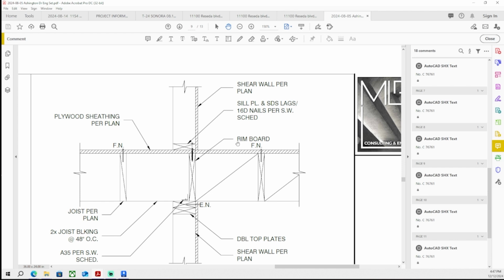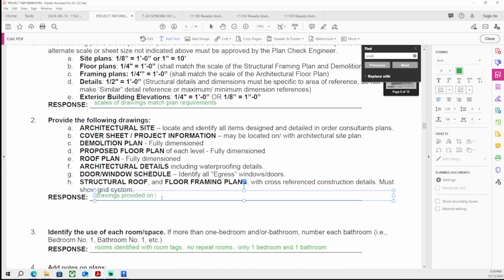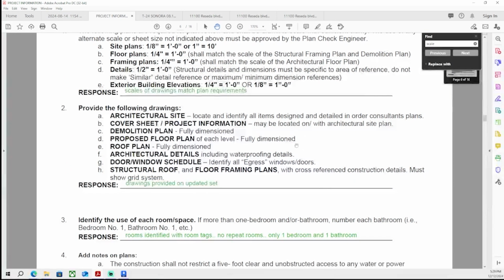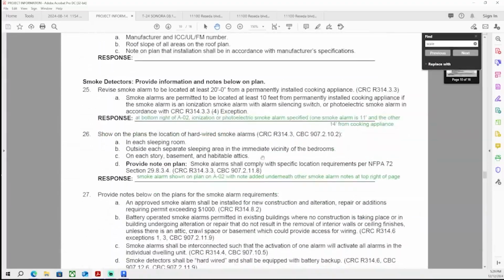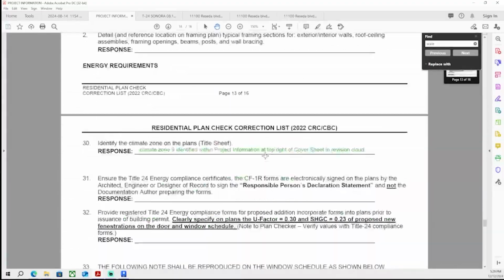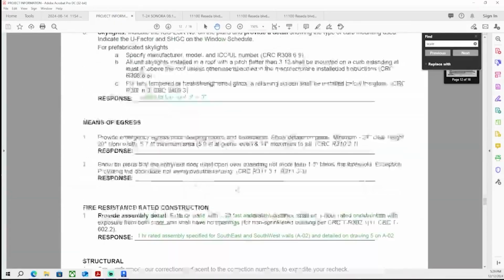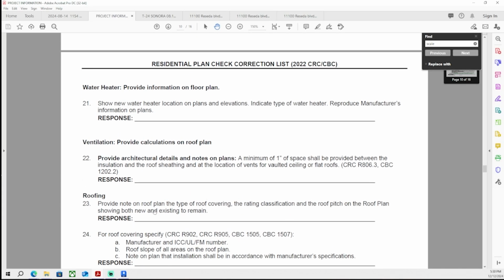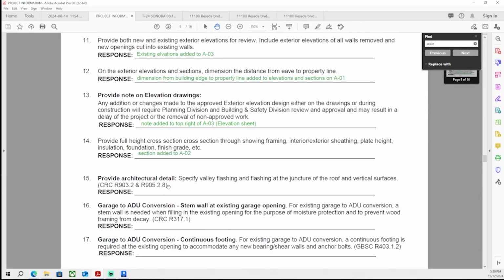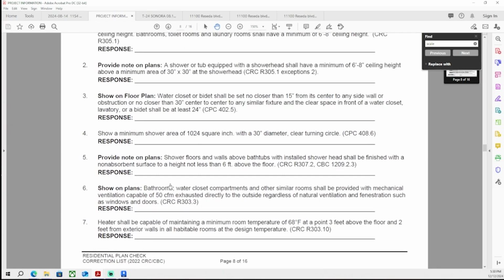So yeah, those walls that are right on the property line end up being just solid walls, no openings whatsoever. Obviously, if you're outside of the setback, if you're within the buildable area per right, then obviously you can have a glass wall. The whole thing can be window. The whole thing can be operable opening.